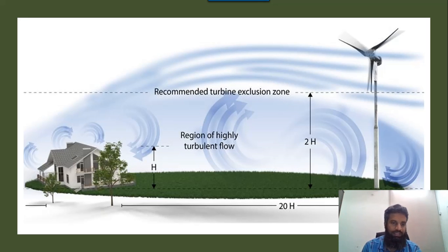In this lecture, I will discuss the design and the basic parameters of the wind turbine. As you see in the figure, you will understand that the size or the height of the wind turbine is based on the turbulence or the objects nearby it. Because if there are objects like homes or trees or buildings nearby, then there is a chance of turbulence in the wind, and the electricity produced is not uniform, and then it will create disturbance in